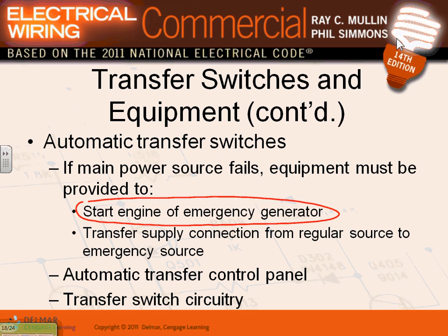Start the engine of the emergency generator or any generator. You have to be able to sense the power lost with the battery and shoot yourself a signal, close a contact to start the generator through the batteries, as it has batteries in the generator. And then, of course, transfer the system.